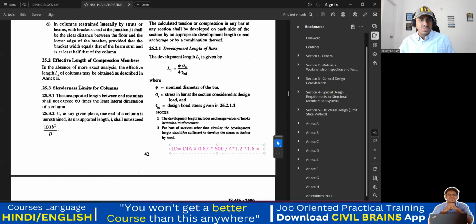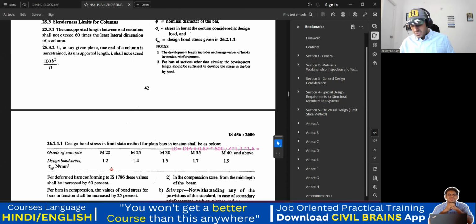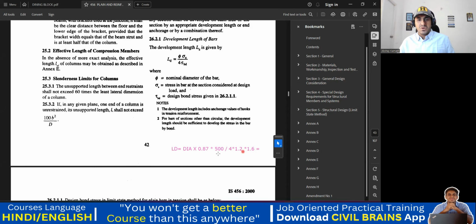We are doing for M20, no? Yeah, 1.2 into 1.6. So I'm getting 54.68. I'll take 55. So it is 55 times the dia.